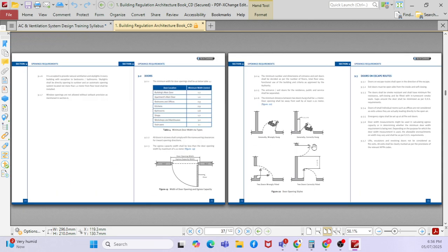Whenever you're a consultant working on design projects, you have architectural, structural, ID, and then MEP drawings like mechanical, electrical, ELV. So whenever you work with architectural, you should know what to comply with your MEP requirements. You will ask for shafts, plant rooms, and different equipment rooms. Whenever you request equipment rooms, you should consider all these requirements.